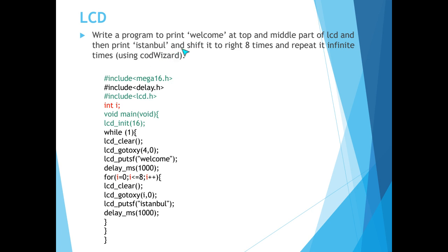But here, because we are using Code Wizard, there is an option to choose our port, and then it's not required to write the assembly code related to interfacing one port, for example port A, with our LCD.